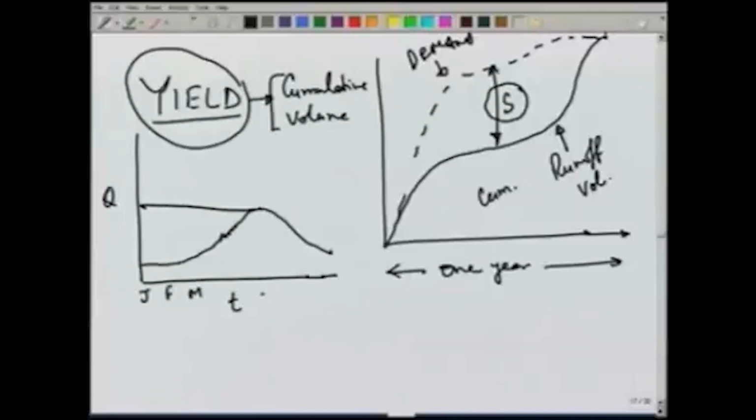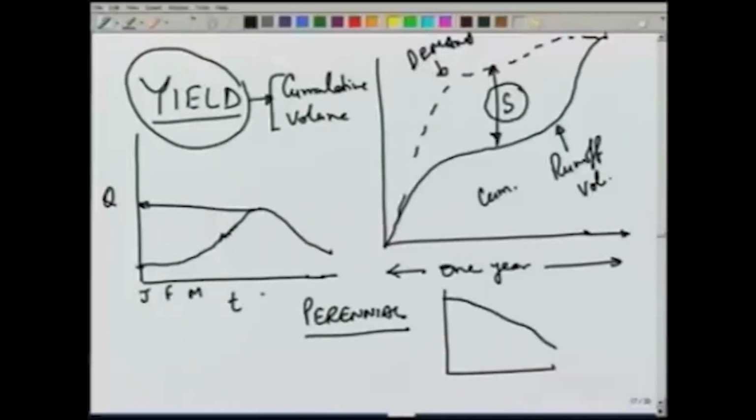Hydrograph will give us what is the maximum flood in the river. So, we can use that to design flood control works. We also have this minimum flow here, and as we have discussed earlier, there are three different kinds of streams. We have perennial, and if you draw this hydrograph for perennial, you will see that throughout the year there will be some water available in the stream, and therefore, if you draw the flow duration curve, the 100% will correspond to some finite non-zero value of q,